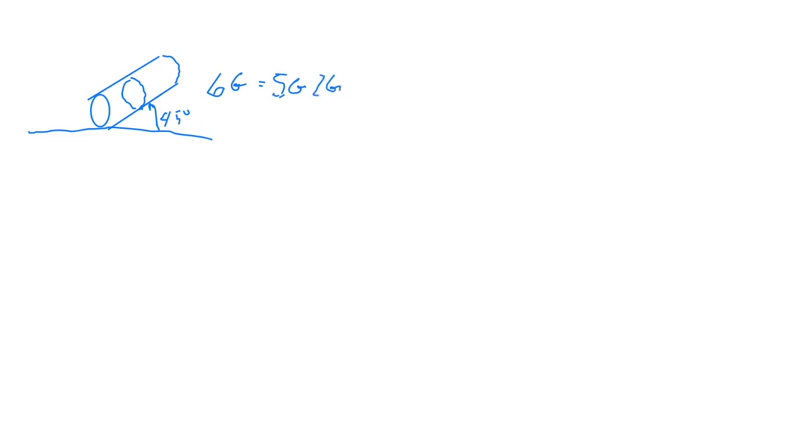Okay, so G for groove weld. Groove welds are harder to do than fillet welds. So here is a fillet weld. This one here is a T. And first I'm going to put in a root pass. Zzz, zzz, and then I'm going to put in my subsequent passes. So I'm going to fill it and cap it, and then I'm going to put in the root, and then I'm going to fill it and cap it. This one's pretty easy to use because all of this material here is called backing material, and it prevents burn through.